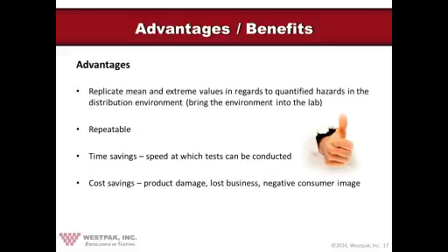So if you do ship testing in order to validate a package system, make sure that you do more than one, and a sample size of many is considered desirable. But that, as Paul mentioned, is one of the reasons why a laboratory test winds up being pretty significant. You know exactly the level of the inputs, and by the way, those levels are generally, we try to shoot for 3 sigma.